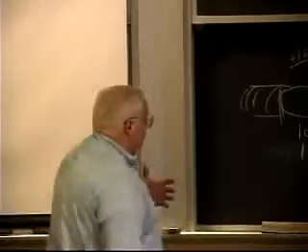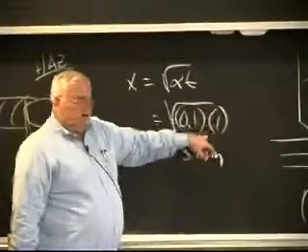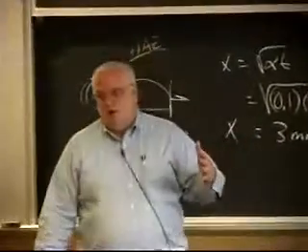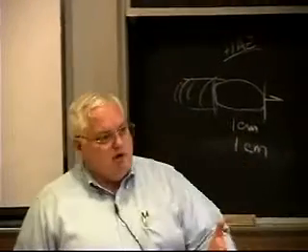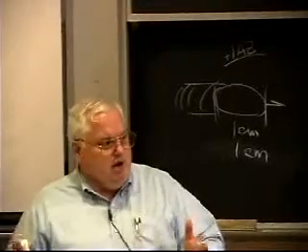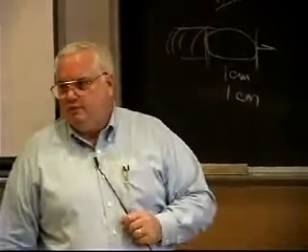Now, if I was in copper, this is 1, this is 1, and so my heat affected zone size in copper is a full centimeter. So in copper, now you can see why I need higher heat intensities to do welding on copper, because I'm really preheating a lot of base material in order to get fusion in the copper itself.